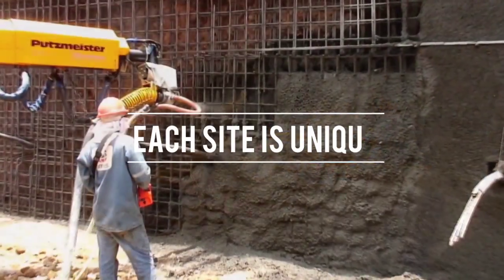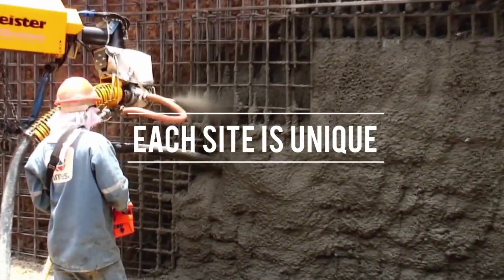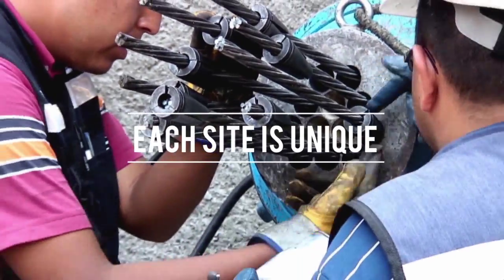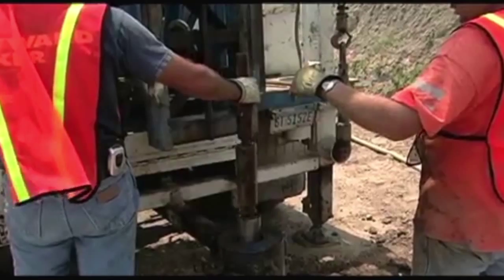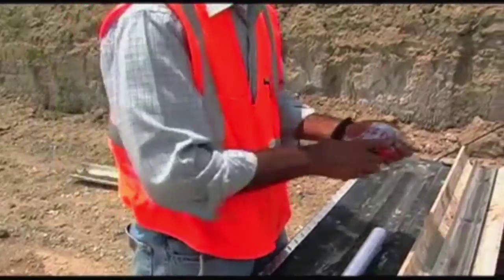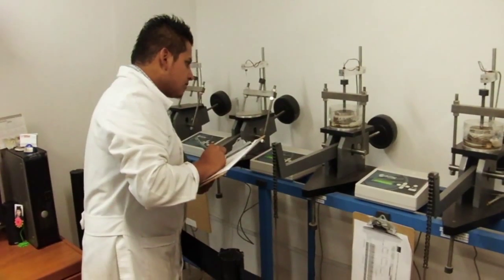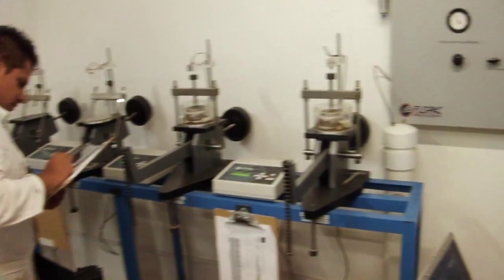Any geotechnical engineering project is different. Indeed, the soil at a site is likely different from any other site. As a result, the most common first step of any geotechnical project is the site investigation. It starts by drilling into the soil and rock layers, testing them in the field or collecting samples, which can then be analyzed in a laboratory.